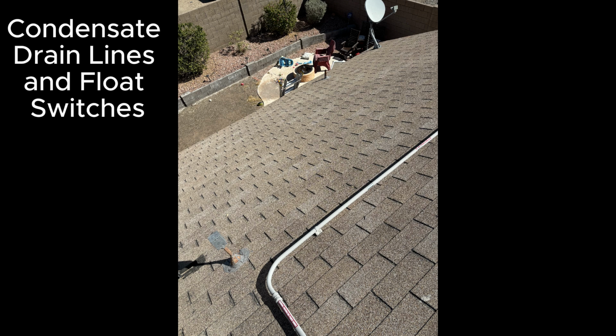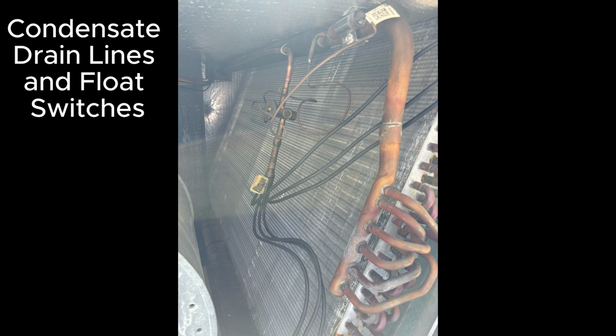The water will move it into the condensate drain line, and that stuff can form a restriction, which keeps the water from flowing, and you could basically clog up that drain line. If the water can't exit there, it will just back up, and you'll have a lot of standing water in that drain pan right where the evaporator coil is located.